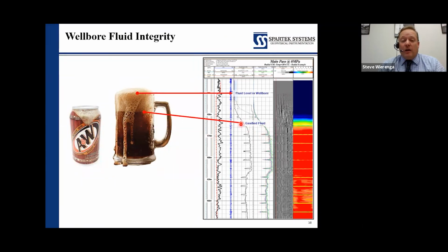So this fluid here, even though it is giving us some acoustic bonding or acoustic communication to the casing, it is not at full strength. We are being affected. We can see that with the VDL. If we look out, we can see it moving in time and moving in this curve away. So on this particular well, when we look at the good level of fluid in our mud and look over our log, it's probably somewhere in this area where our waveform stops breaking away and the air is no longer affecting our acoustic signal.